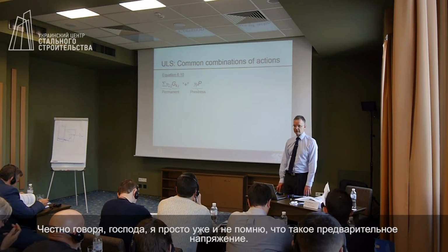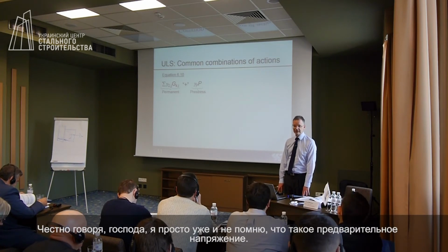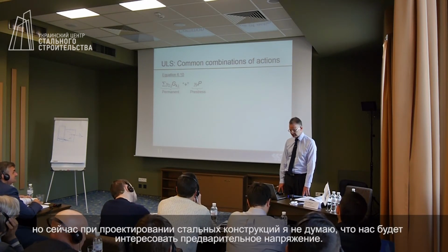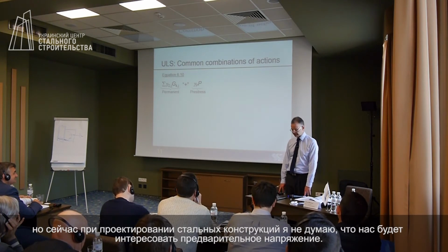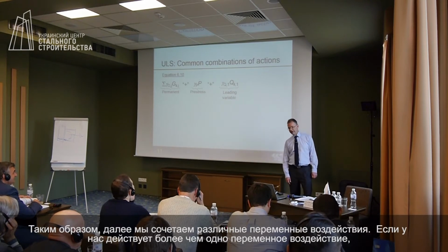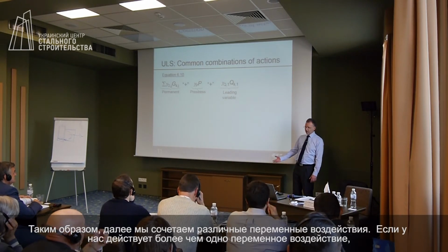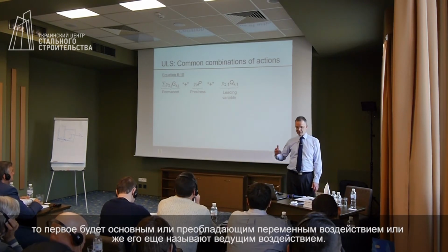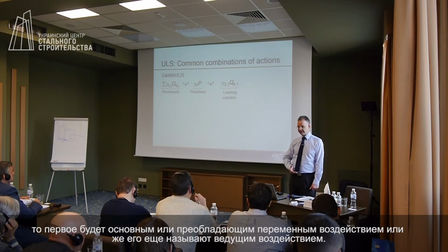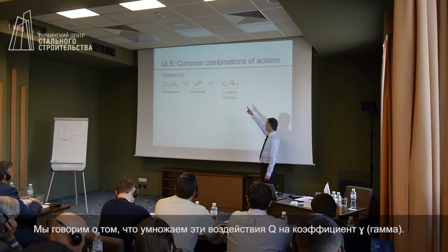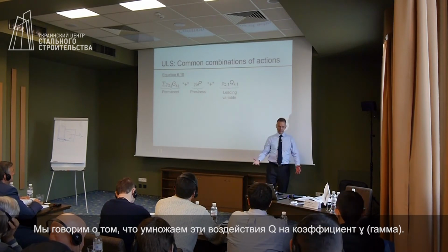I can hardly remember, ladies and gentlemen, what pre-stress is. I remember doing it at university, but in the steel world, we are not interested, I don't think, in pre-stress. So we combine it then with a variable action. And if you have more than one variable action, this first one is known as the main variable action or the leading variable action. And all that is saying is there's the variable action Q multiplied by a gamma factor.